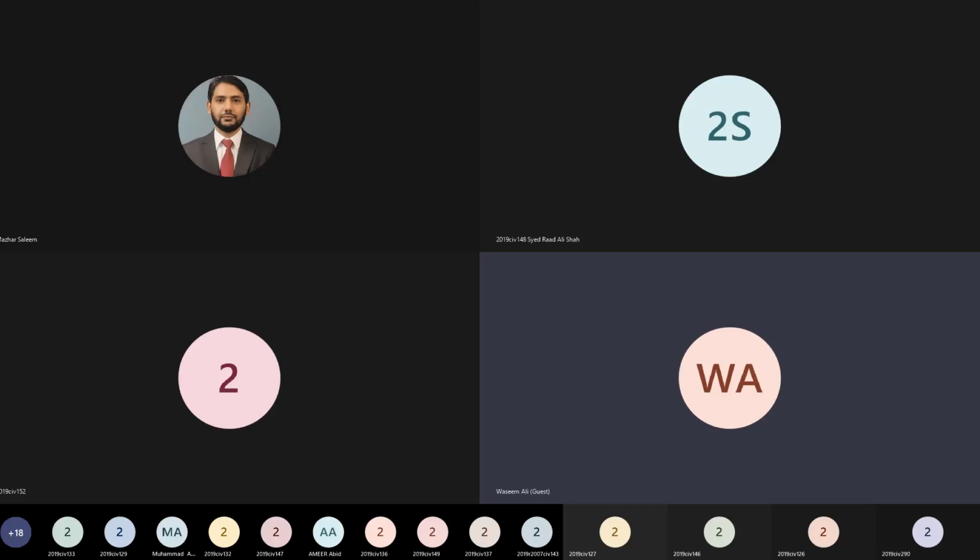The main scale reading in that case is exactly 3 millimeters. The large scale needle is ahead of 3 millimeters, so you will read it as 3. And again, you will have to read it indirectly because the scale is graduated in the clockwise direction, but the needle is moving in the counterclockwise direction. Similarly for the small scale reading, once you reach the 100th division, after that you will have to read in the opposite direction. The small scale reading shown in that image is 117.